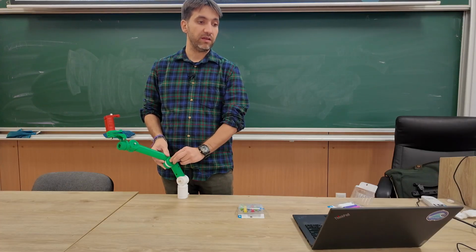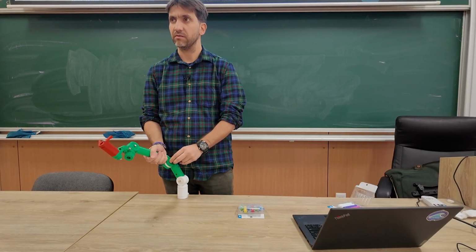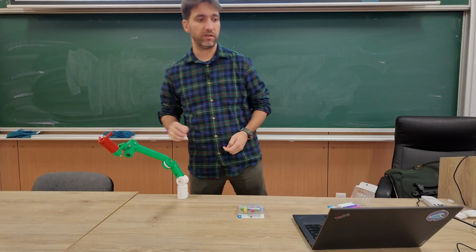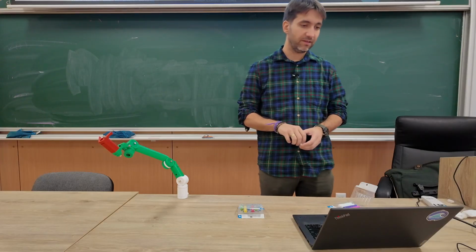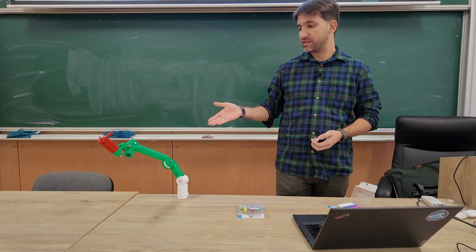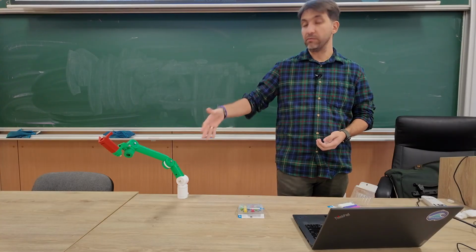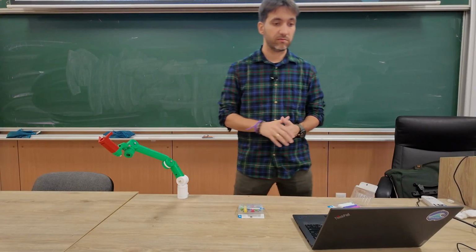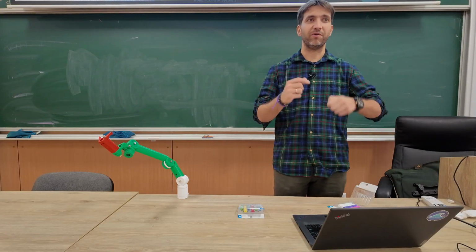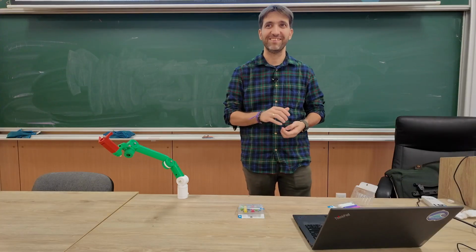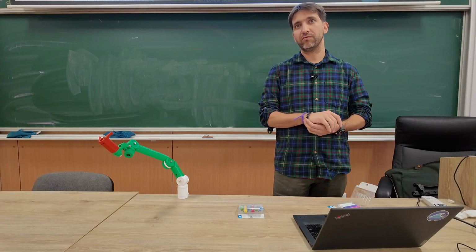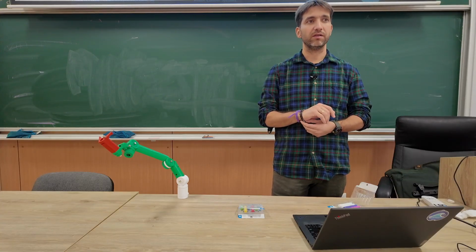Can I use a PID to control this? Why not? Because it's single input, single output. Great. It's a SISO controller. Single input, single output. While in this case, I basically have multiple inputs and multiple outputs. So what do we do? Can we apply one controller for each one, one by one? All right, so we have one separate controller for each joint. That's one idea.